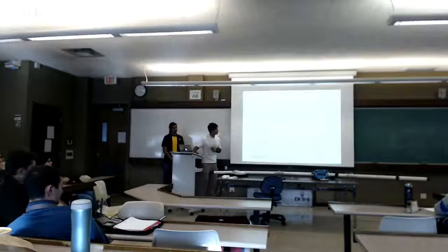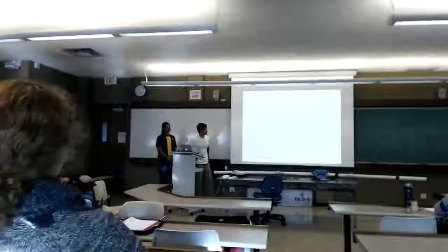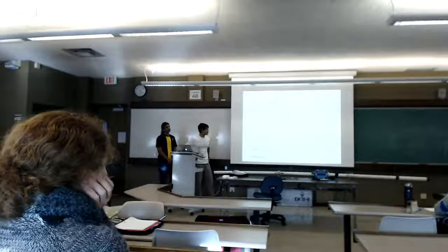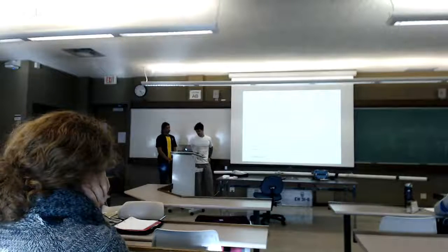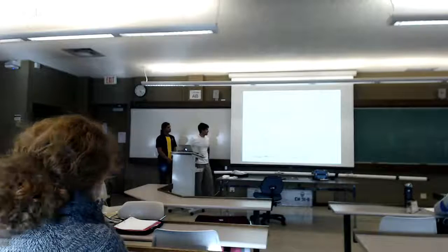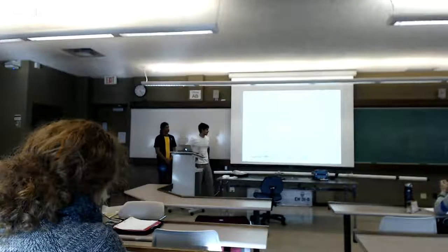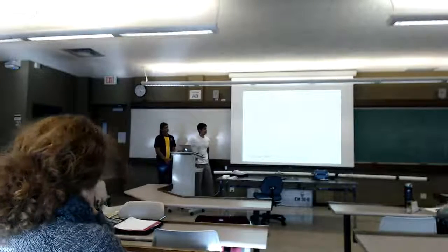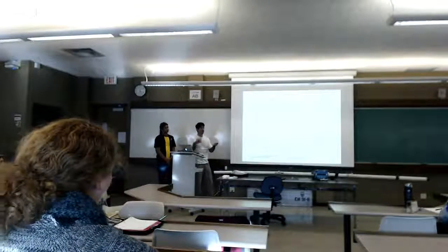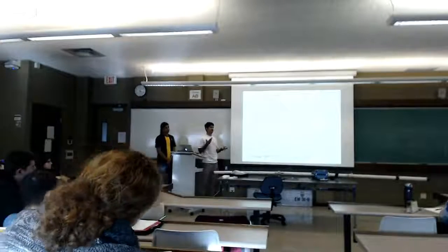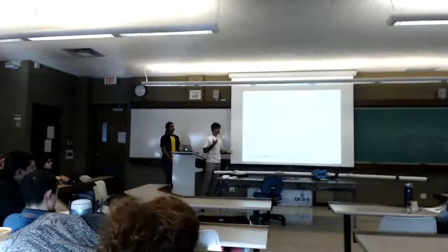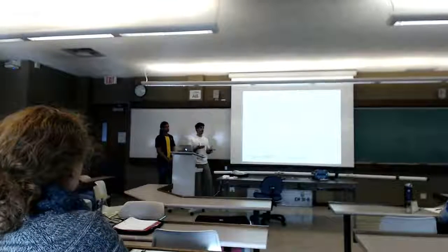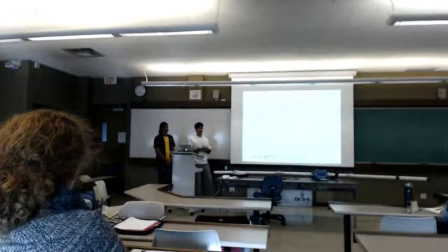So do you take soil samples then and test for all of these things? Yeah. In our project proposal, we proposed several borehole sites on site and around our site, and that's how we would have tested for any contaminants. We're still in the process of looking at the data that we've obtained and figuring out which contaminants are actually on site and which exceed the standards. There might be some contaminants, but if they don't exceed the current standards, then we don't have to remediate for them.